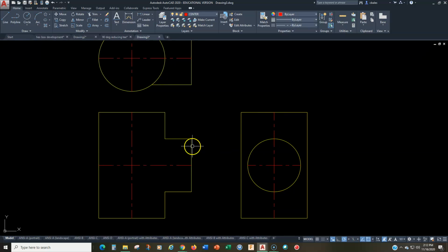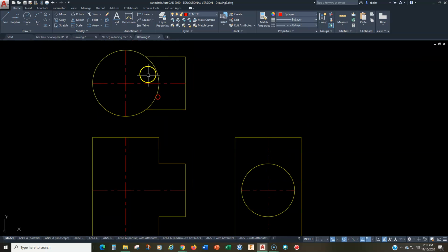We're trying to draw on this surface right here where this edge coincides. And what's interesting to note is that we already have the line of intersection in the top view and in the right side view. We already have that done. How so? Well, it's this edge right here. Here, let me show you.